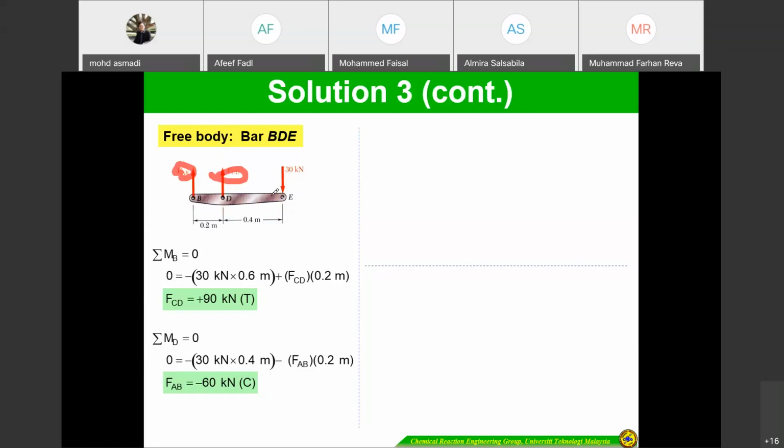So the method that you have to use for the equation of equilibrium is the moment. That is the best equation that you can use, rather than Fx as well as Fy. First, we determine by using the moment at point B equal to 0, so that we can reduce the number of unknowns to only one.